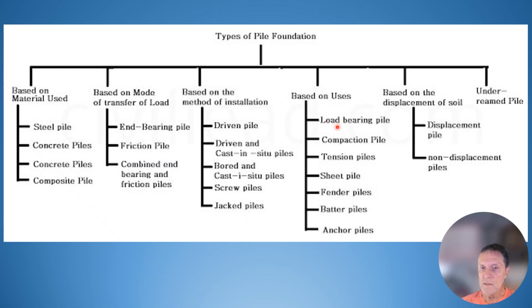Different types of piles: load bearing, sheet piles, compaction piles. There are piles that you drive in and you base the design length and depth on the displacement of soil. Okay, so there are different considerations that go into the design of a pile foundation, deep foundation, and the type you might use at a particular site.